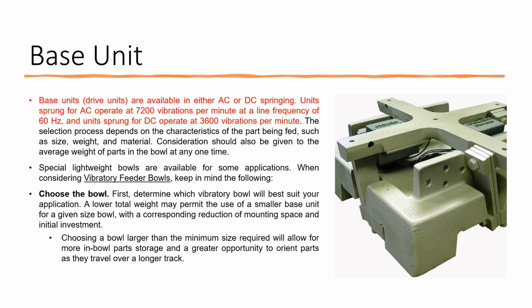Then we have the base unit. As I discussed, the base unit is nothing but the drive unit, and it can be available as AC/DC or a pneumatic system. It will create the vibrations, and you can see the vibrations per minute and the line frequency. These parameters will decide how the parts get separated and sorted out, and at what rate we are getting them. That is why the base unit selection is very important.